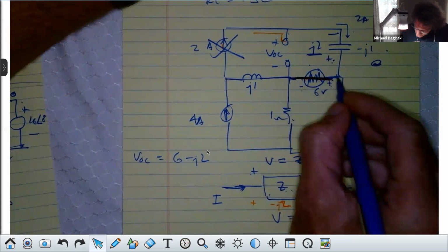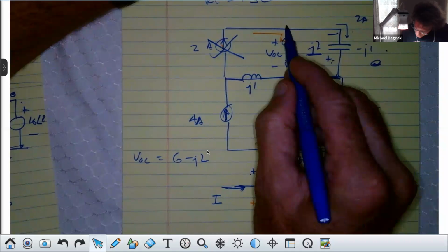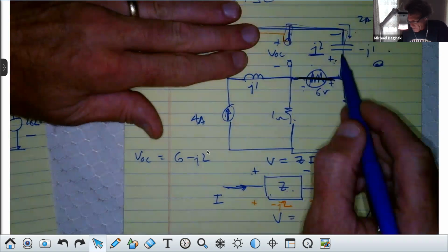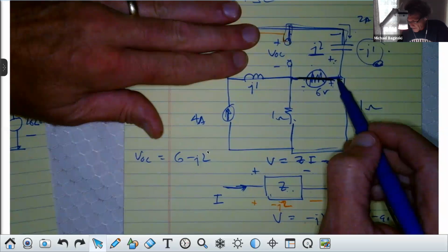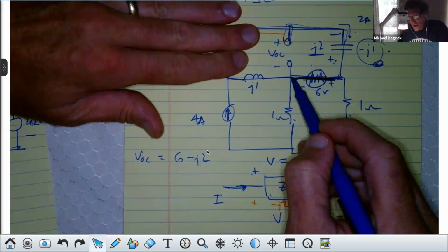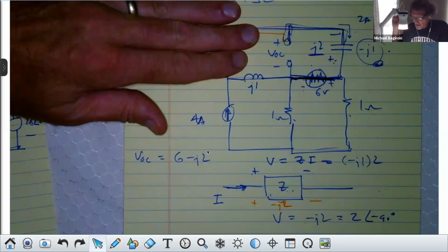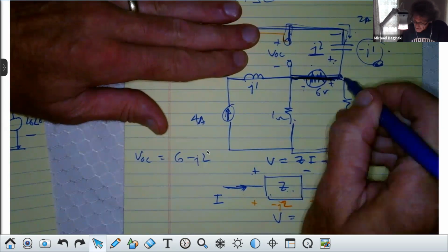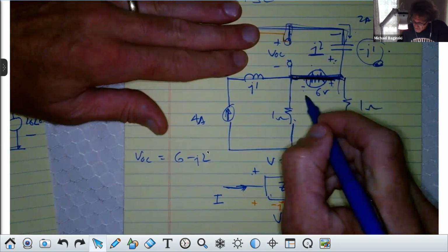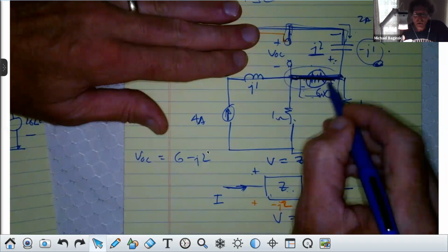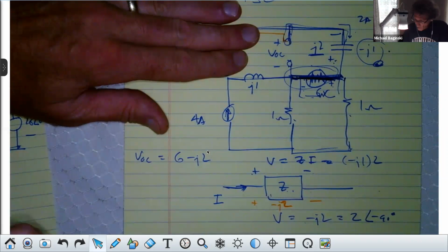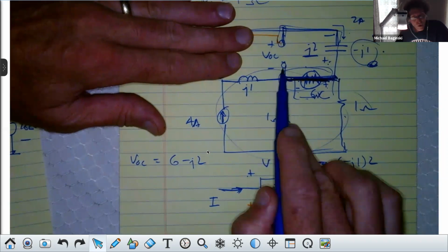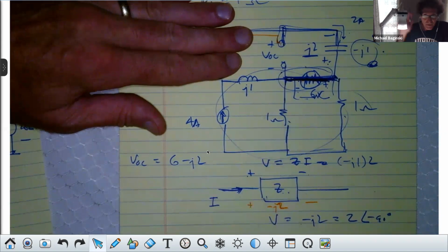Now take a look at this. I got a short circuit, I got an impedance, and if I look at the impedance across these three terms, this is an open circuit, you ignore that. I just have minus J1 ohms between here and here, don't I? How many see that? None of this stuff matters because that's a short circuit. So the impedance between here and here is zero. I can put any value of resistance across that and it's still 0 ohms. Do y'all see that? It's a short. All this stuff has no bearing at all on the Thevenin equivalent impedance. How many see that now?